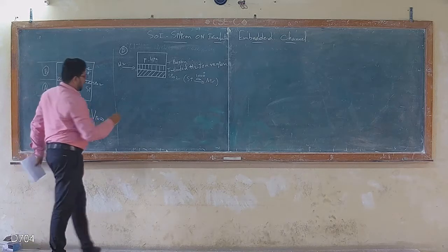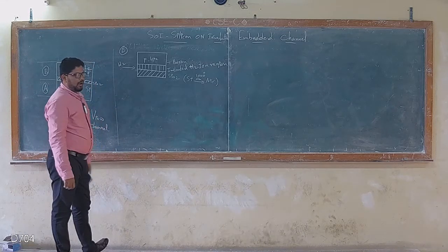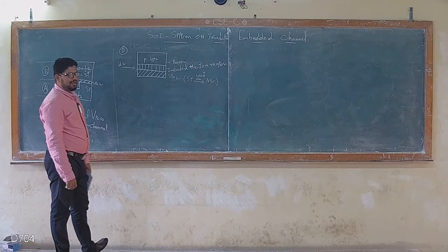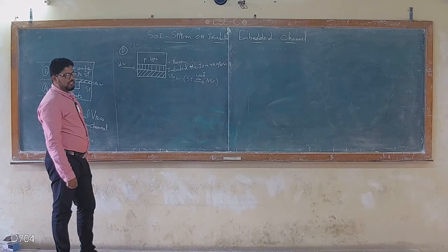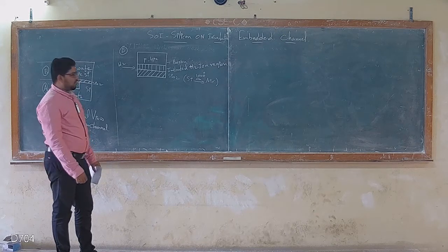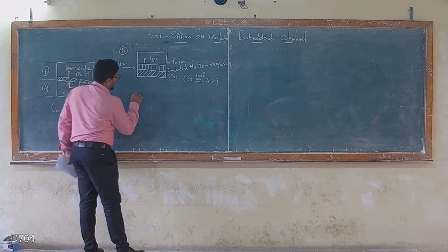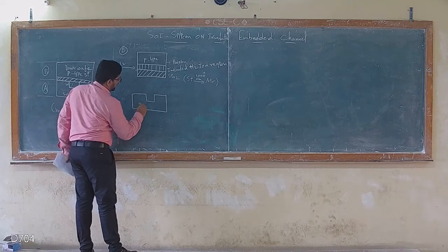But downstairs, I have a microfluidic channel. Using soft lithography, or either dry etching, wet etching by chemicals, plasma etching, or even deep reactive ion etching, you can use any kind of etching. It is easy to form a channel on any kind of silicon substrate.